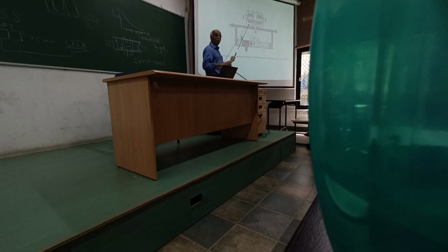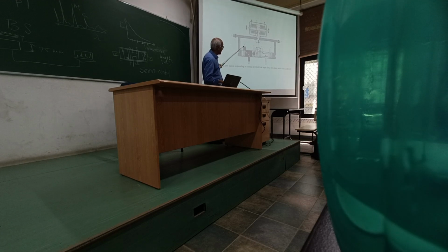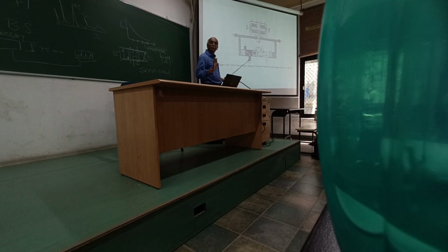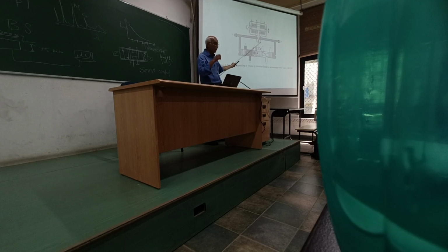In this case, I want to control this spool position. Fluid from P will go to either C1 or C2, and when it goes to C2, the output from C1 will go to the reservoir or tank. I have copied this from some other book where the tank is represented by a reservoir R. So this is the way it works.